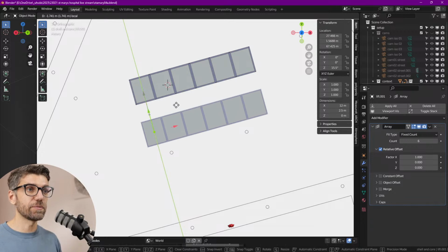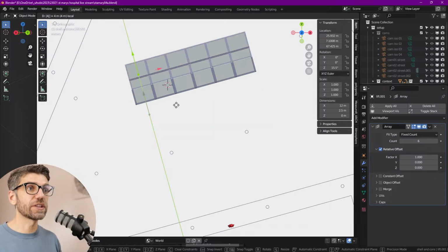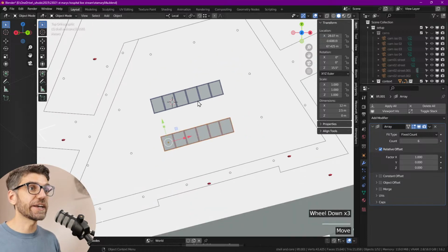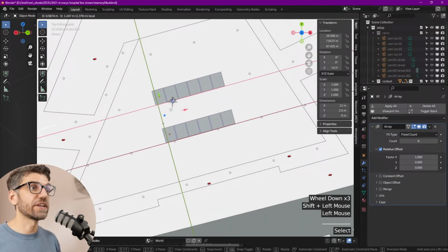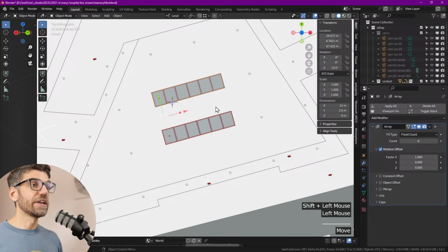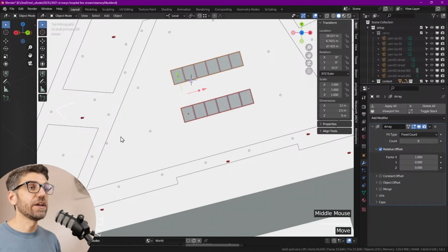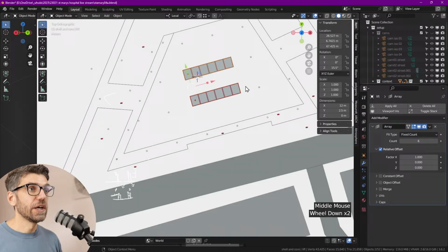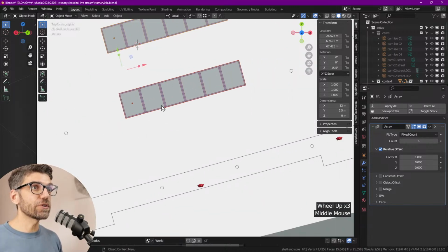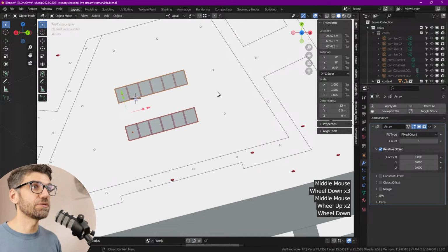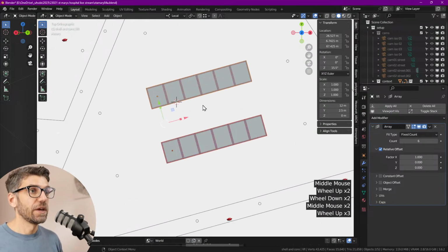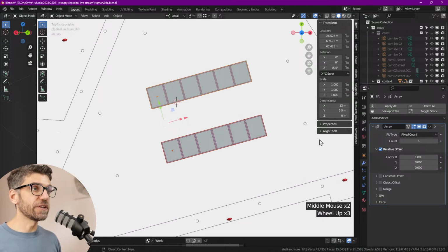But in our case, it might be a lot of people waiting here, some in wheelchairs, some doctors, some sick children. They want to have a little bit of space, so we should probably go with at least 4 meters in the negative direction. So that's our core. That is at least the core that we need, and we can put that nice and generously in the center there. Once we have this core over here, what else do we need? We need a couple of emergency cores. This is not something you typically look into in a lot of detail, but you need to be aware of it, because it takes space and we need to design our core around it. Not absolutely necessary, but definitely important.